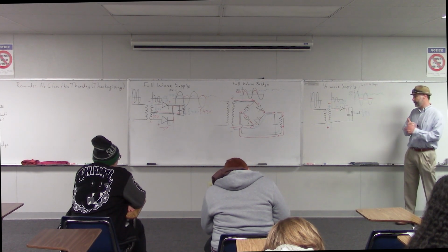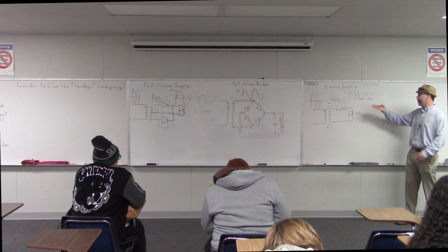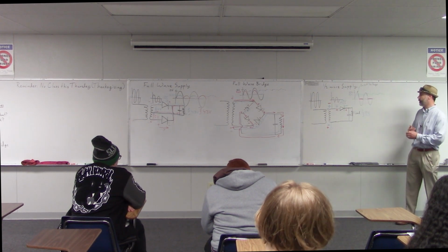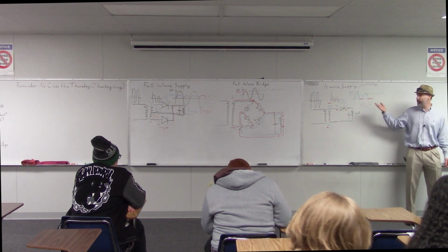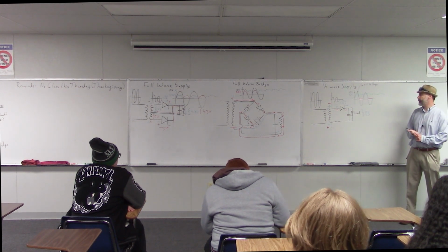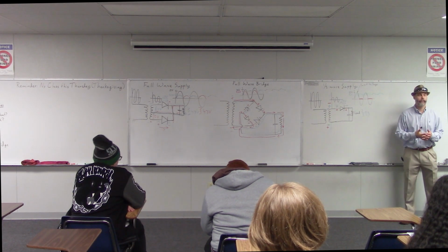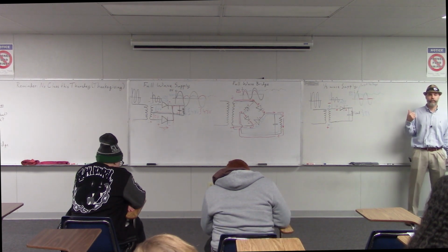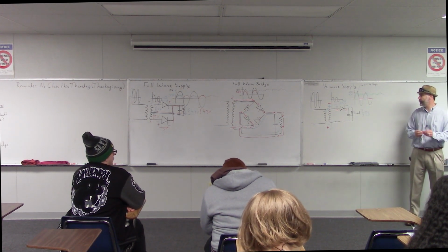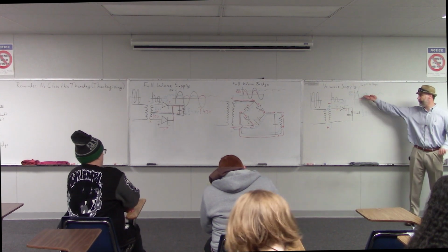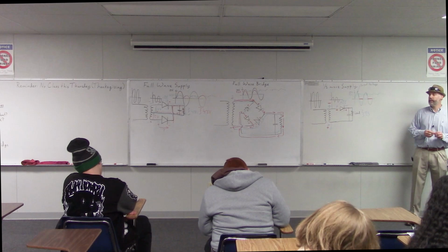So advantages are cheap and easy to build. Disadvantages are a lot of ripple, and also efficiency. It's not capturing half the wave. It's just throwing it away. So it's somewhat inefficient that way. Is there also a lot of stress on the capacitor? I don't think so. As long as you stay within the voltage rating of the capacitor, it should be fine.